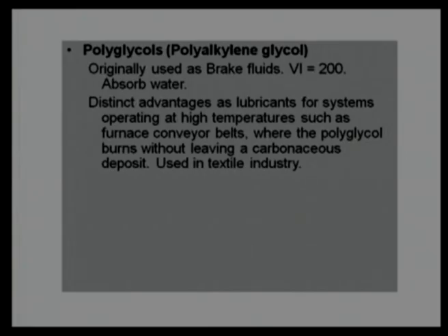We tried to utilize this kind of polyglycol in our magnetic bearing setup, where the desire was low lubrication requirement and film thickness was maintained by the magnetic repulsion. If we would have used high viscosity oil, there would have been much more shearing of that oil, much more heat generation, but we used a brake fluid which has low viscosity, a viscosity equal to 2 centistokes at 100 degree centigrade.